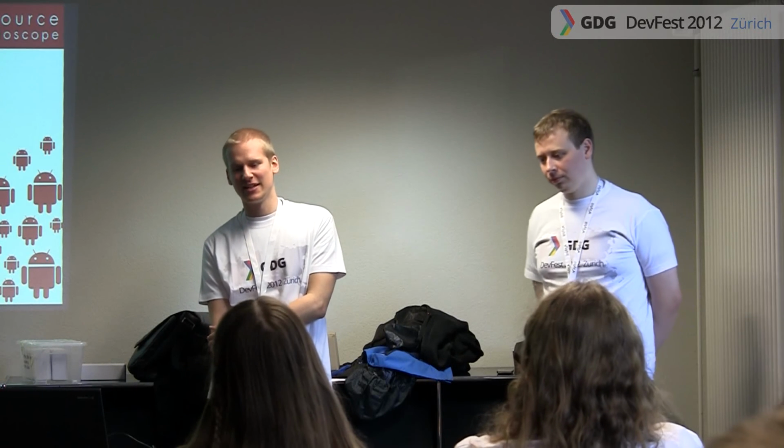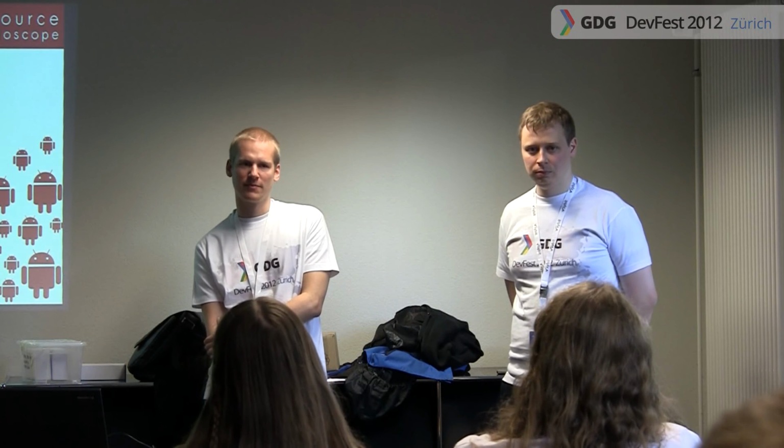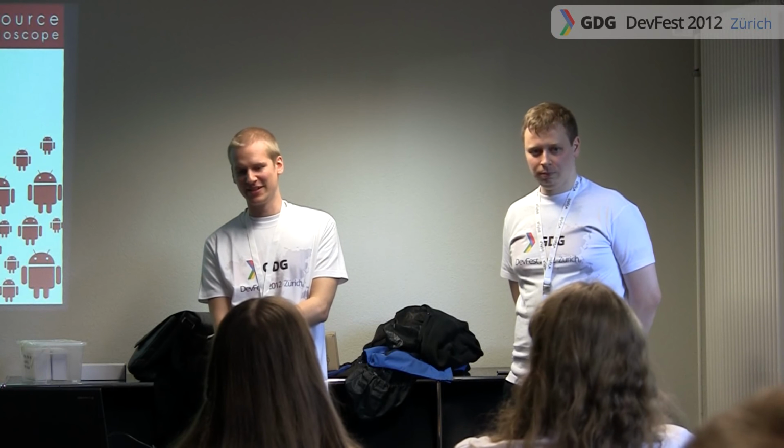Only if you really know what you're doing. Or you could, for instance, use another probe. We designed it for 10-to-1 probes. If you use a 100-to-1 probe, then you can measure higher signals, of course, as well. But it's untested from our side, and we wouldn't recommend it.